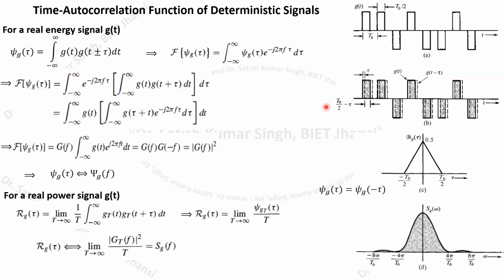So that time this multiplication gives you the maximum value. And when we vary tau from 0 to some finite value, the correlation between the two signals will start decreasing. This particular product is going to decrease. Normally this is the autocorrelation function that I have defined.